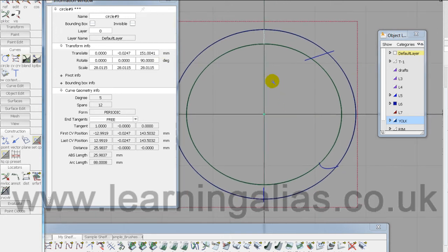Okay, now we want to rotate this around here, and I want to avoid these two curves which are going to be features in my kind of stitching, material joints in my steering wheel. So I don't want my patches to interfere with those in any way. So I'm going to come to about here. So this is 45 degrees. So I'm going to pick 55 degrees.